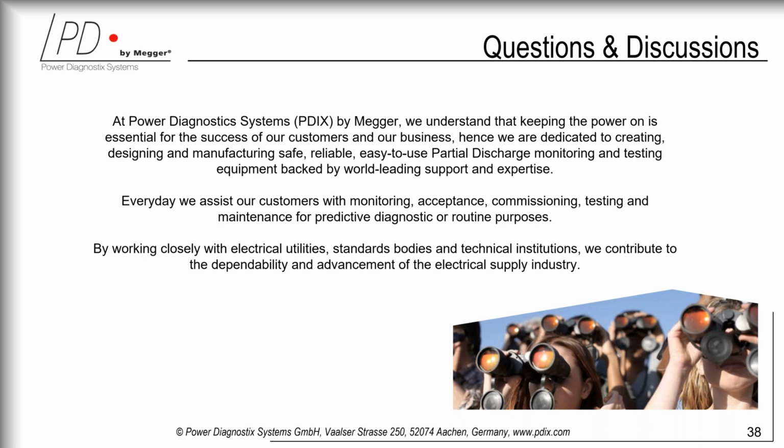We are looking for partial discharge in general. Wherever partial discharge is present that we can tap into the way we described with our sensors, we are going to find it, and then we will declare the severity of it, either via alarms or via more in-depth trends and patterns.